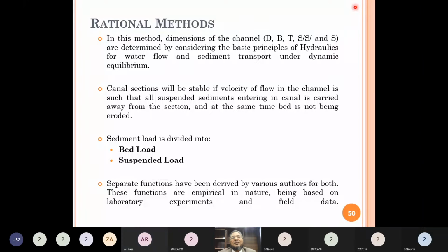Yes, so Khala is water course. And is this water course a government owned or farmer owned channel? Farmer owned. Okay. So the last irrigation channel which is government owned, what is its name? Minor. Minor is the irrigation channel.